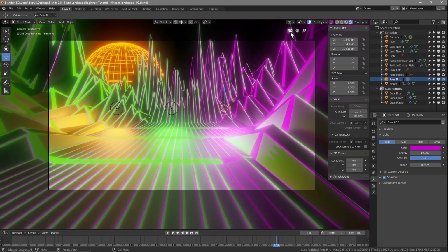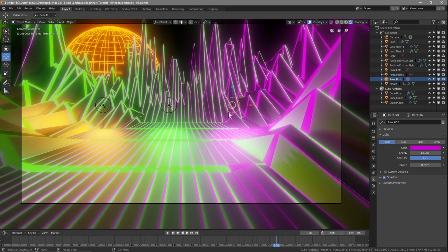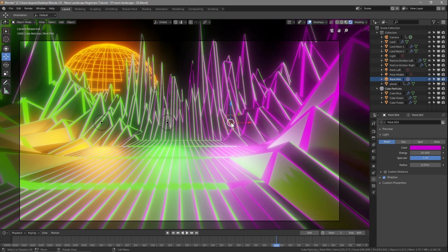So we're already in camera view, right? Yep, we're in camera view. Let's press N on our keyboard. That will remove this transform panel. We can zoom in, and we can hold down the Shift key and the middle mouse button just to get our camera to see as much of what the camera is going to see. This is what the camera will see.